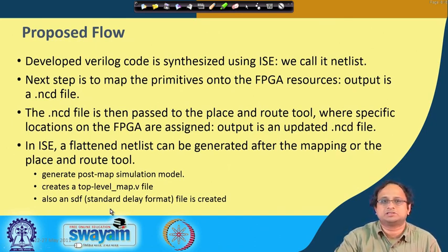So, .sdf or SDF stands for the standard delay format. This particular file contains the delay or the parasitic delays of your circuit. You have the various gate delay information and the routing delay information. Pretty much whatever the tool is predicting about your design is noted down or recorded in the .sdf file.